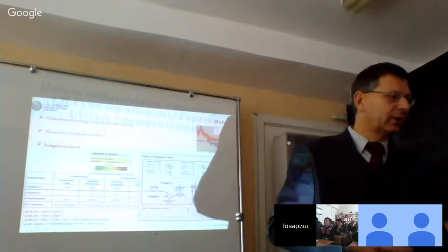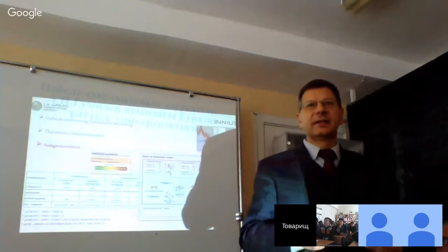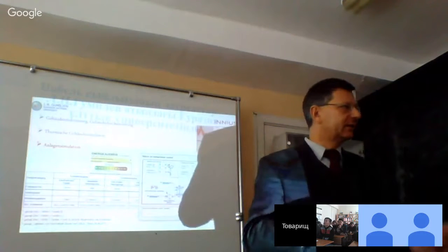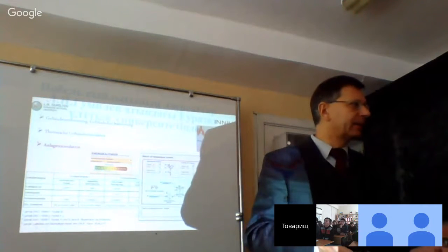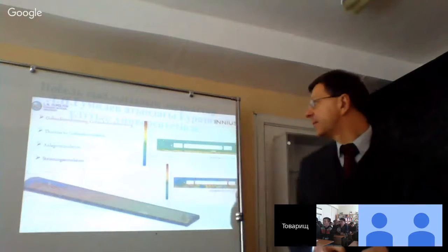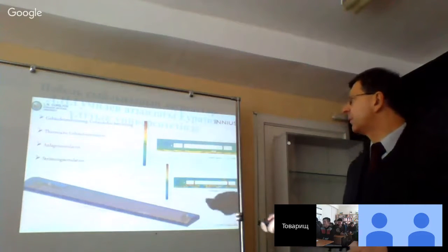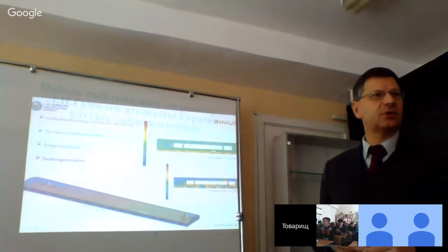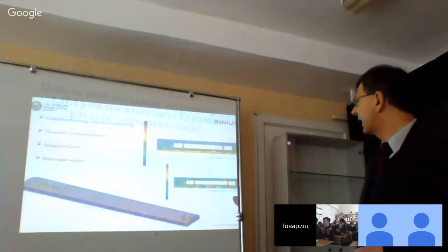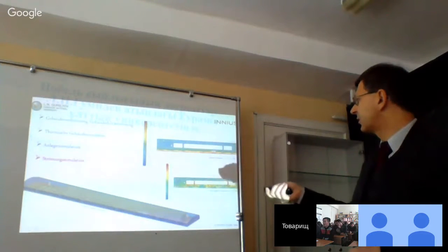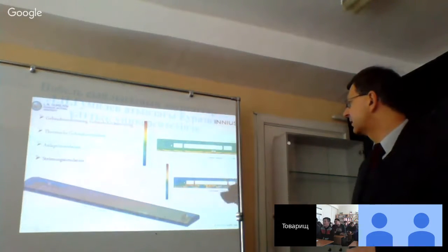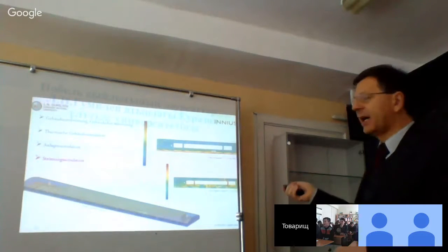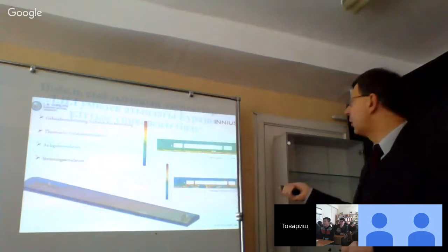But what we do not know at this point is how to reach the air with the energy, the point where we need the energy for the air. That's the question. And for this, it's possible to perform airflow simulation, so-called CFD, computational fluid dynamics. There you can estimate, for instance, for such a terminal building, the Terminal 5C in London, the temperature distribution at a height of 1.50 meters above the floor.